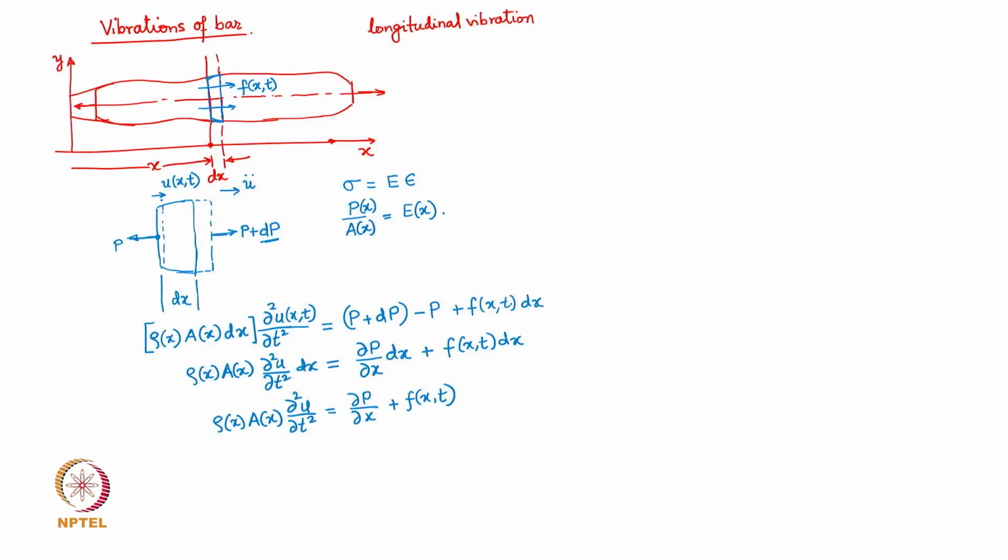Okay, so if the deformation on this face is going to be u(x,t), the deformation on the other face is going to be u plus du. The deformation on the other face could be slightly different, a slight change in the value. That slight incremental change is going to be du. So how much is the net stretch in the element of length dx,